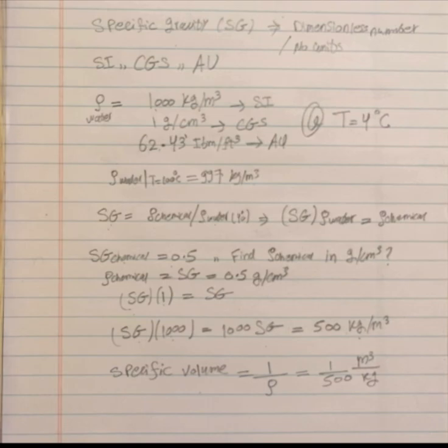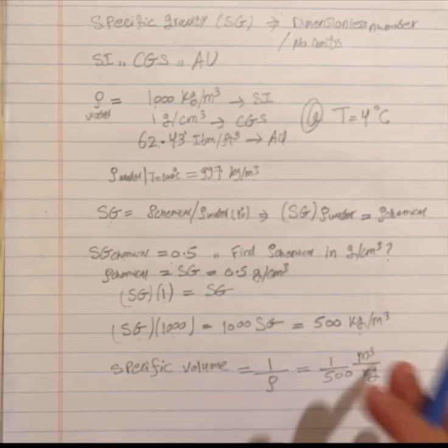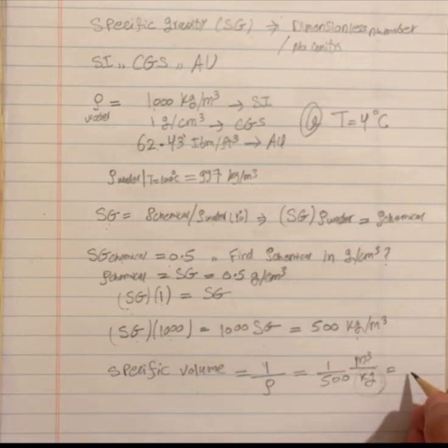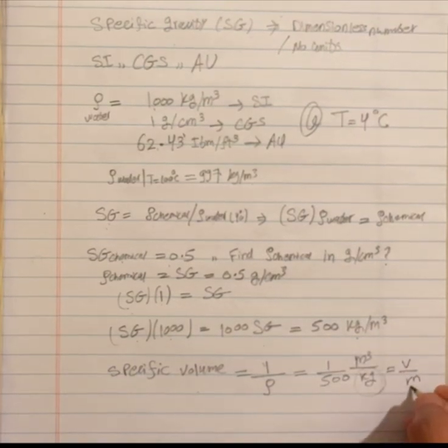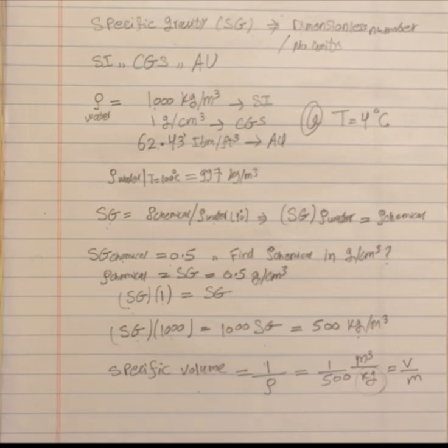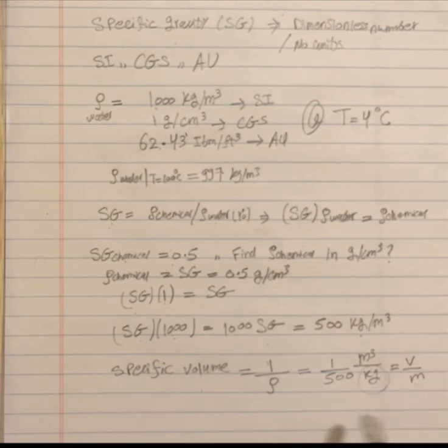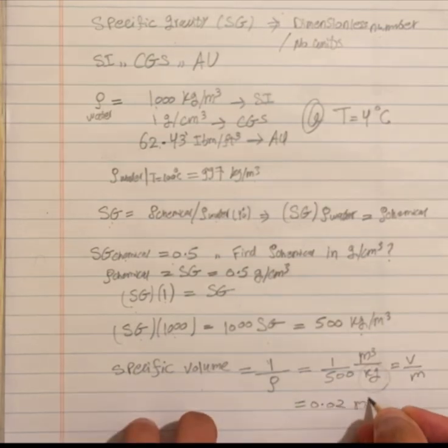This is specific volume if you divide volume by mass, because remember, I also said in the previous video that whenever we say specific and then a word after it, like volume or enthalpy, then you either divide by mass. Here in this case you divide by mass, because this 1 over rho is actually equal to V over M. Or you divide by moles, but I will come to the story of moles later on. For now you can say specific volume equals 1 over rho, which in this case is 1 over 500, which is V over M, which is 0.02 meter cube per kilogram.